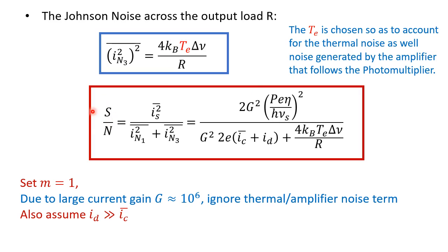So my signal to noise ratio is basically the signal itself, divided by the shot noise at the photocathode itself, and the Johnson noise, right? And so you see this Johnson noise is sitting in here. We have ignored the dynode noise because that was 1 by delta of this shot noise contribution.